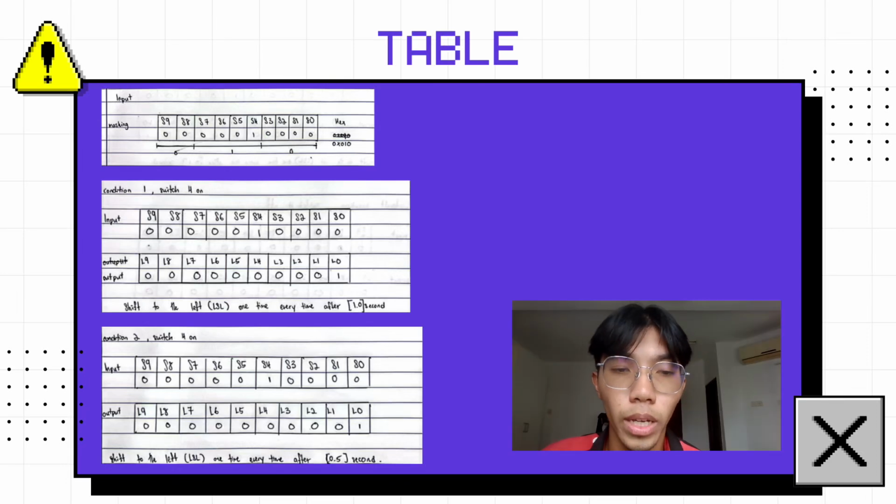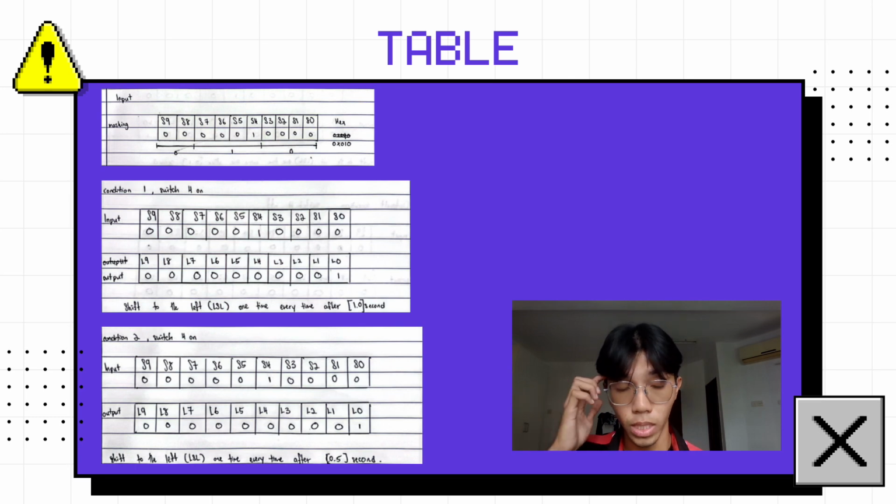So now, let's look at how the processor actually interprets our hardware inputs and outputs at a binary level. The first one is switch inputs and hex masking. If you look at the top diagram, we have our 10 slide switches labeled S9 down to S0. To isolate switch 4, we apply a software mask by setting bit 4 to a logic high 1 and all other bits to 0. We get the binary pattern